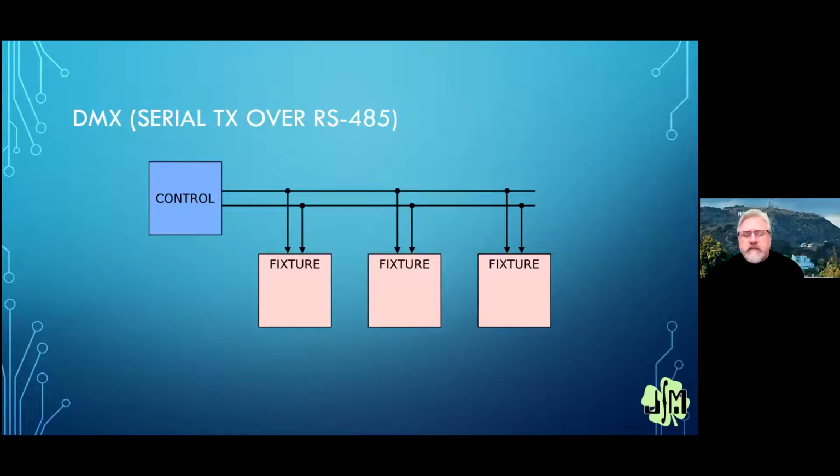This is important because, for example, in lighting, as lighting fixtures age, their color changes, and this can be problematic. And so fixtures, for example, will keep track of how long they've been operating or what their temperature is. So you need a bidirectional thing in that. In DMX, it's just one way. In RDM, it can go both ways, but it's running on the same hardware.